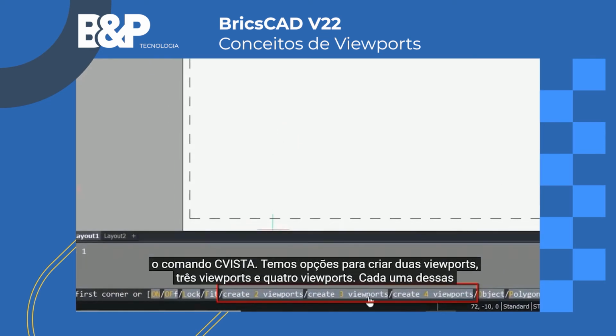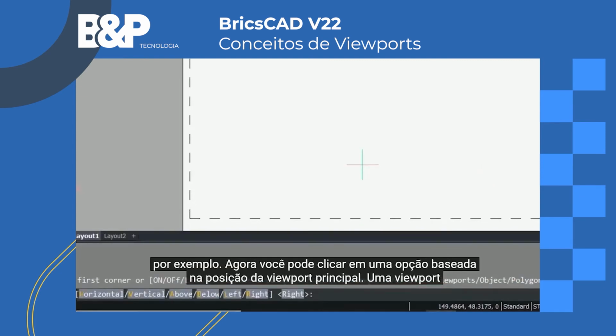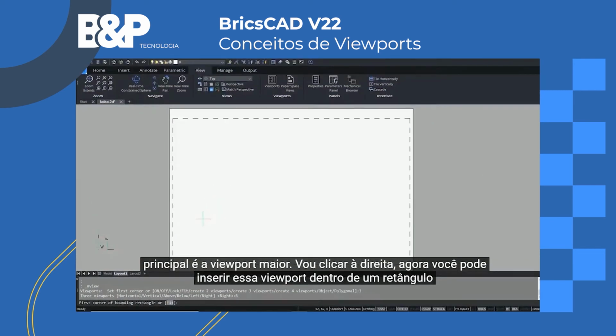Repeat mview command. We have create 2 viewports, 3 viewports and 4 viewports options. Each of these options will let you create predefined number of viewports. I'll click on create 3 viewports, for example. Now you can click on an option based on the position of the major viewport. A major viewport is a larger viewport. I'll click on right.